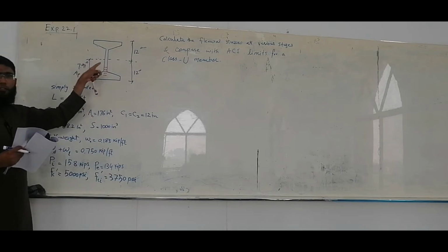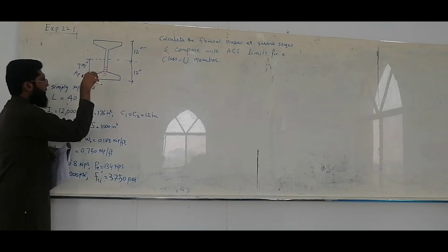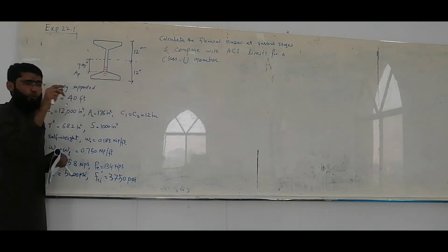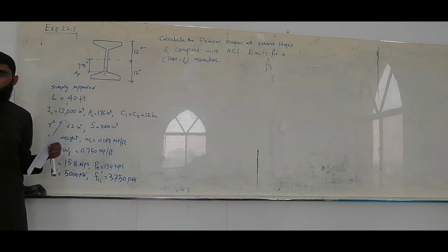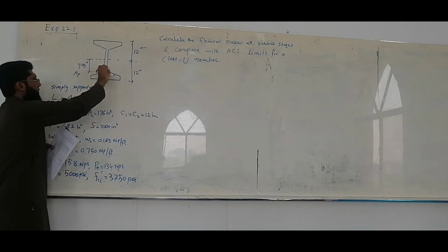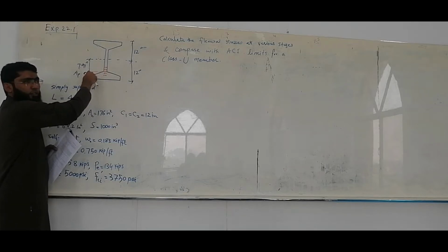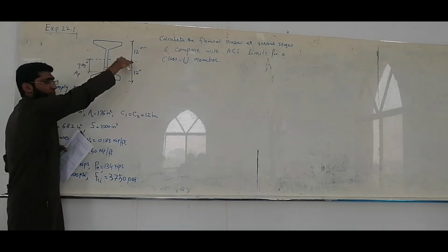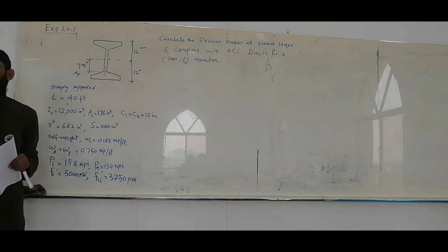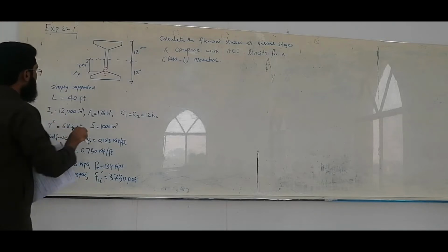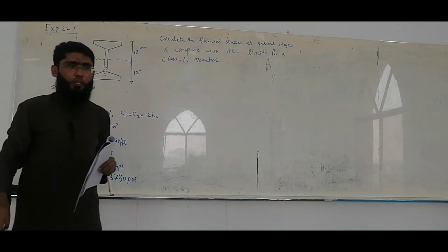Okay, so there are multiple tendons, and each one of them is a 7-wire strand. Each of them has a certain area. There is a table for it, but right now we're just discussing that they have a certain total area, and the centroid of them is somewhere over here. So 7.9 inch below the centroid. This is the centroid of the whole section, and this level is the centroid of these strands. There are 5 pairs at the middle third. At the third one, you have the centroid. So they are all the same areas.